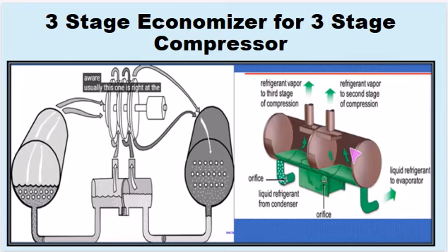The clever part is the economizer. Imagine it like a heat exchanger where the hot refrigerant from the top floor helps warm up the cold refrigerant from the bottom floor, saving energy just like using the steam from your shower to help heat your bathroom. The refrigerant then goes through the condenser, like a radiator, where it cools down and becomes liquid again.